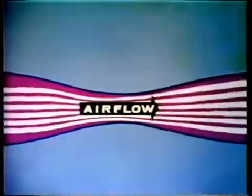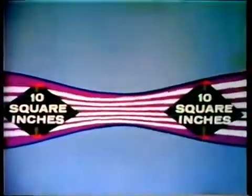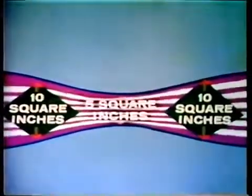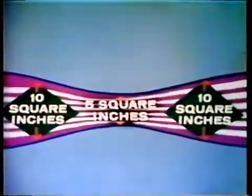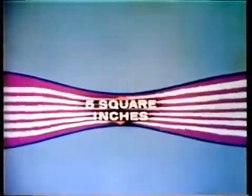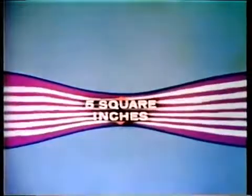First, note that its pattern suggests it is passing through a tube-shaped device. Next, notice that the entrance and exit of the device are the same size. We can measure the openings and find that the ends are each 10 square inches. The middle part is squeezed, creating a throat of 5 square inches. Now, if we direct smoke lines through the device, its pattern will show that something happens to the air where it goes through the narrowed part.